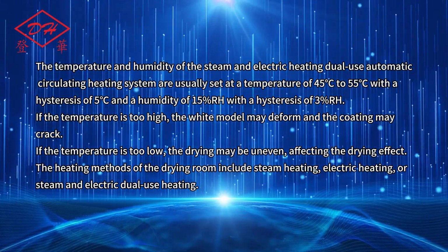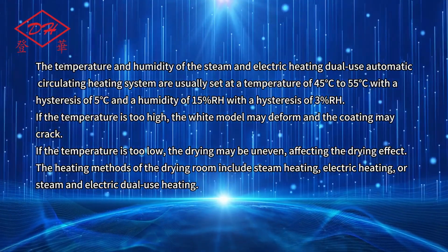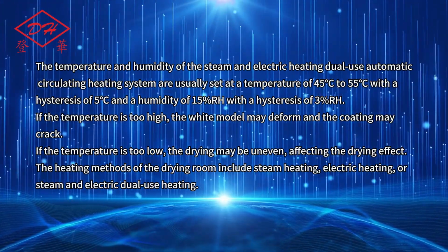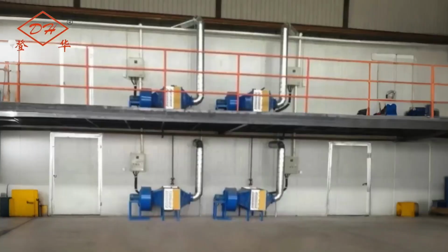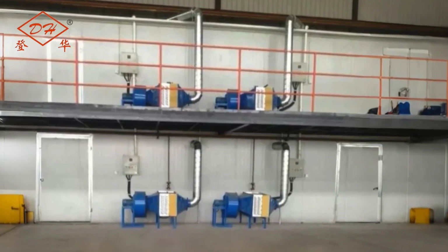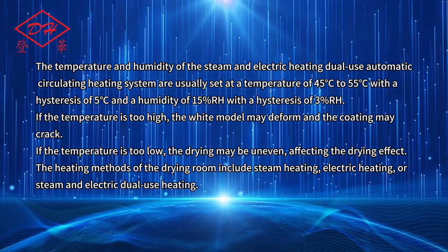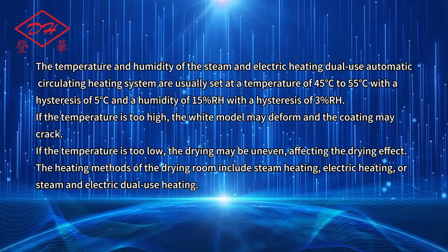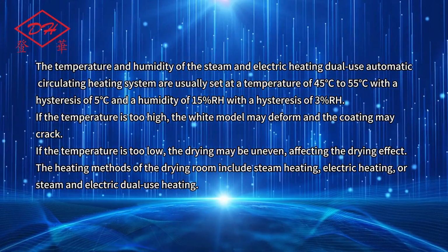If the temperature is too high, the white model may deform and the coating may crack. If the temperature is too low, the drying may be uneven, affecting the drying effect. The heating methods of the drying room include steam heating, electric heating, or steam and electric dual-use heating.